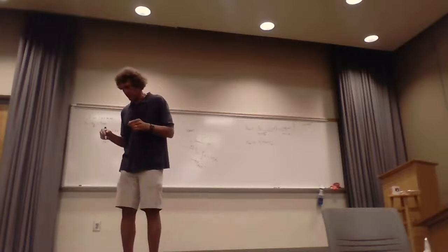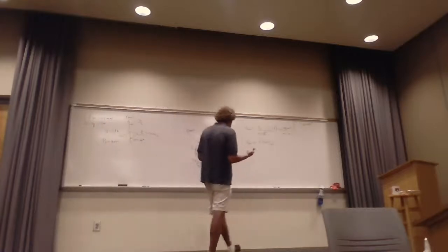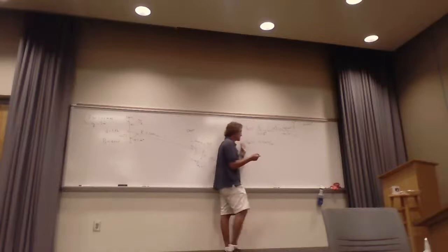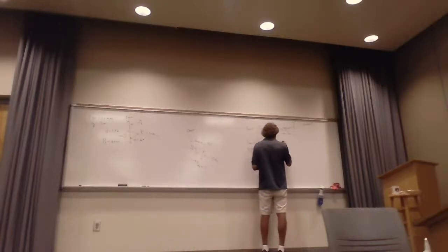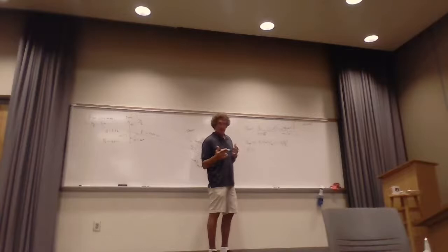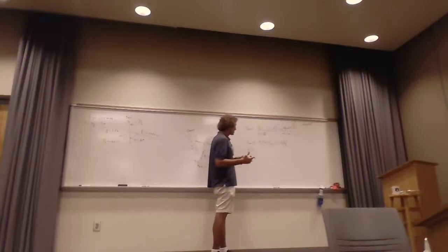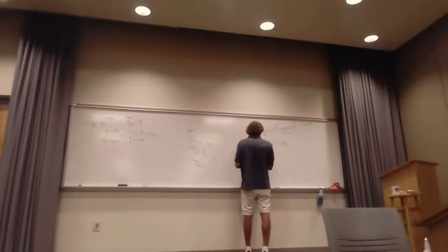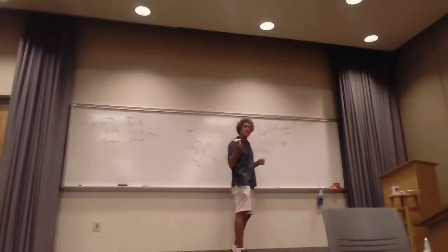Electric field incident on antenna 2. Yeah. All right, so this is again the same old stuff. So for the E field magnitude, I know this is equal to 1/2 magnitude of E squared over eta naught, because it is free space, right? I'm trying to make sure this is as real world as possible. So here it's just the square root of 2 eta naught times average power, right?